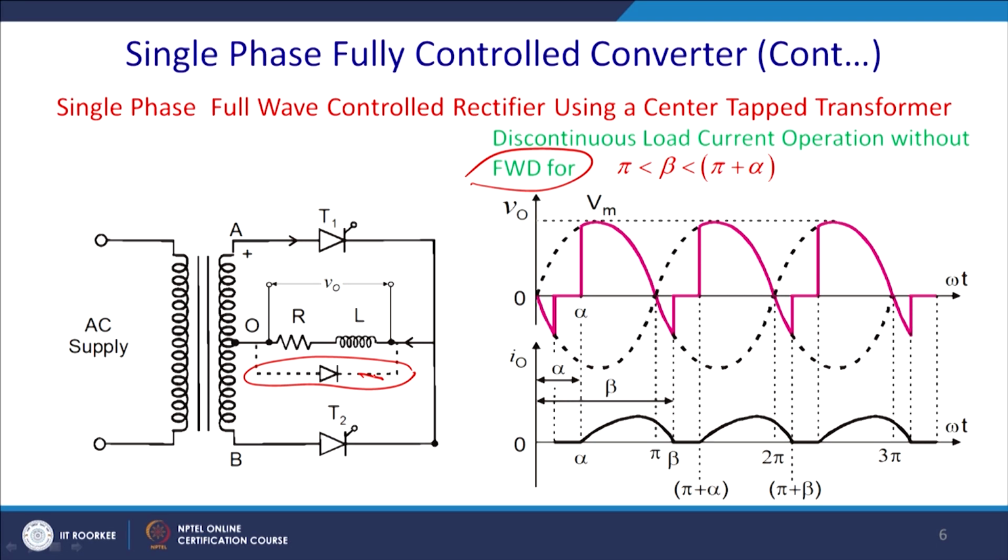So, what will happen? Negative voltage will come, that gives rise to the ripples or more DC, and thereafter at the triggering angle alpha, it will conduct. So, stored energy will make these thyristors conduct even in the negative half cycle. So, you get this profile. All the energy is discharged during this time. So, for this reason there will be no voltage available, and in the same way it will continue.